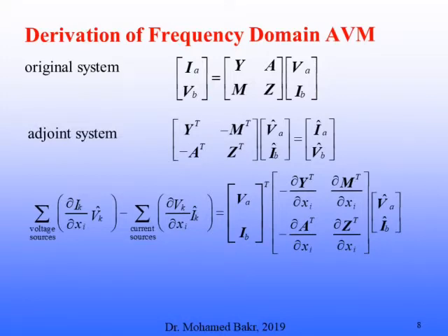This division, or this notation, allows us to handle things like transformers, like transmission lines. We can include them in this derivation. You write how every current is related to the voltages, and you can see that the current in one branch, for example here, can be related to the current in another branch. So you have a current dependent current source as well, or something like this. You can see that the voltage in the branches B can be related through the matrix M to the voltages in branches A. So this can be used to handle a voltage dependent voltage source and so on.